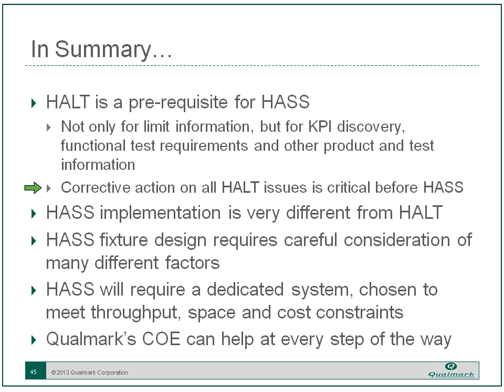If you've found something in HALT, make sure it gets fixed before you get into HASS. Keep in mind the implementation is different. It takes planning. It takes a lot of people involved. It's treated like a project, and you'll get it done right. And there's a lot of things to consider with fixture design, the table, the product, the potential for damage, the potential for damage to operators. All of that has to be considered. And remember, you'll want a dedicated system, chosen to meet the throughput, space, and cost constraints.